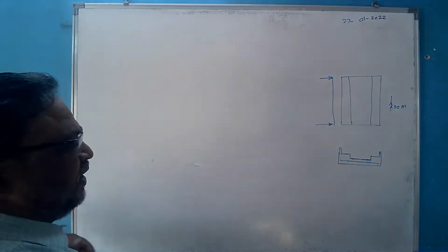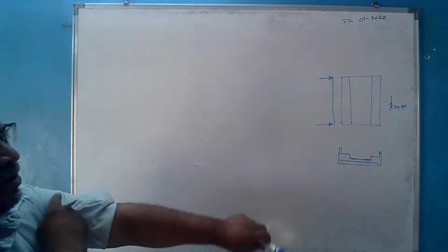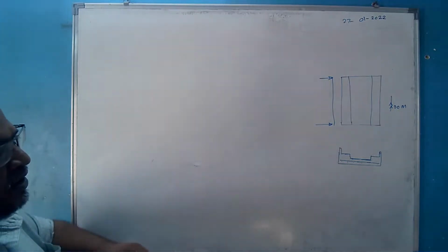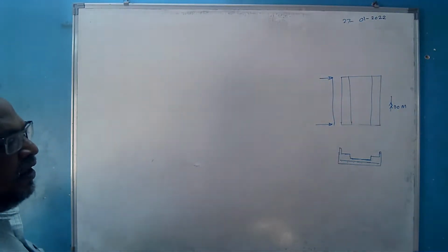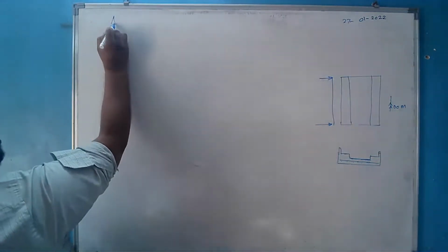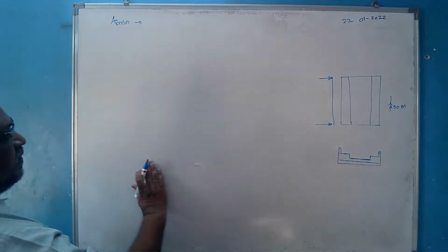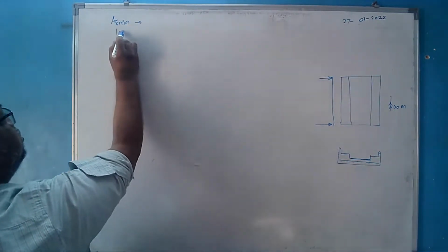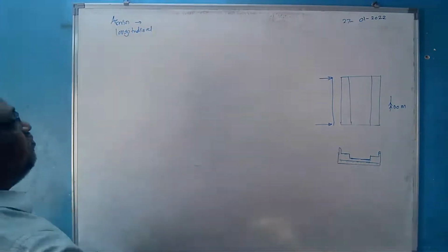From the ductility criteria, limit state of serviceability, and limit state of cracking, we had determined the minimum area of steel to be provided in the direction of length, that is longitudinal, that is in the direction of span.